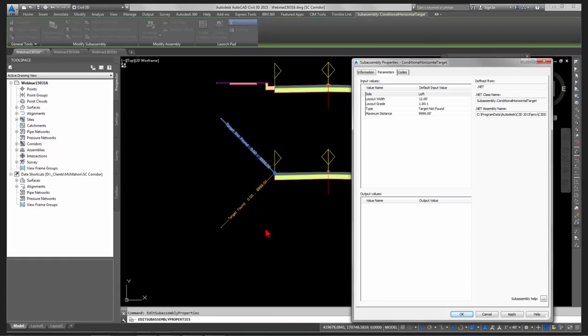I can have multiple distances in here. And that's what I see here is I actually see the max distance right in here. So I have the ability to say, hey, if I find this line, but within the first 200 feet, just in case my corridor may loop back on itself, I don't want it to find it 10,000 feet down the road.